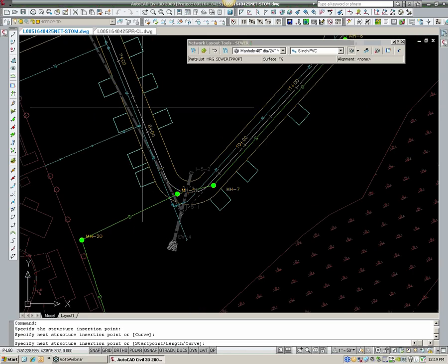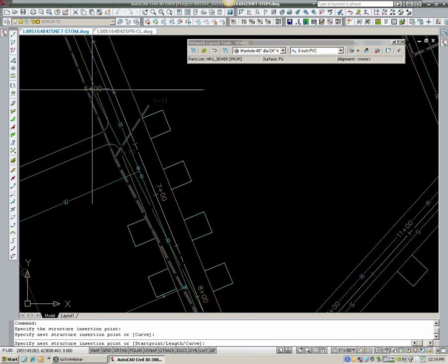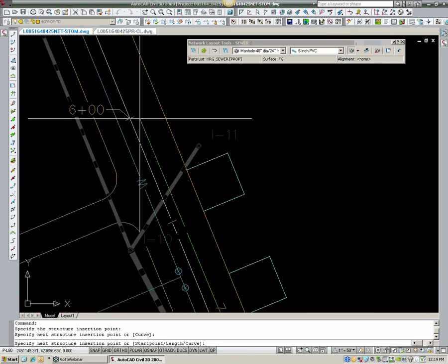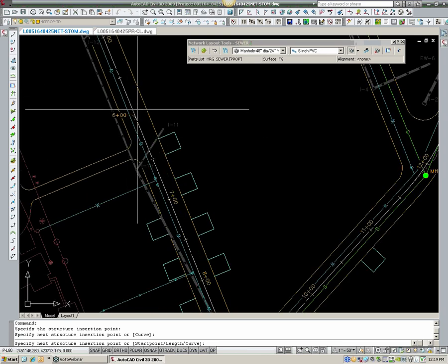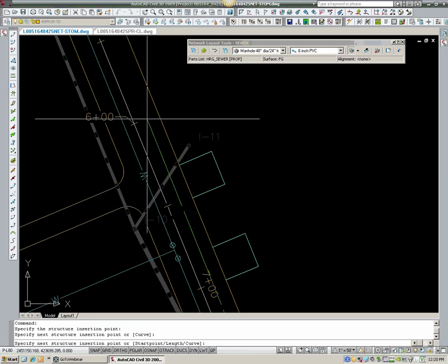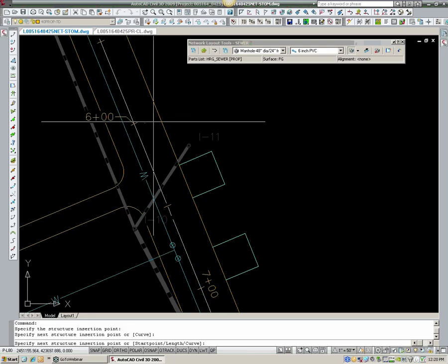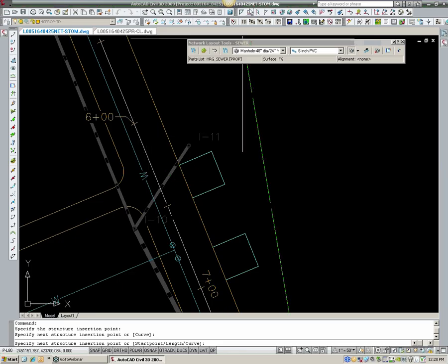Okay, well, I'm going to come up through here, and we can only go so far with our manhole run. So maybe up here around station 600, I want to place another manhole, because it can only have 400 feet of length and so on and so forth. But when placing this, just eyeballing these in, I want more precision than that. I want this manhole center to be right at station 600 and exactly 5 feet to the inside. I want it to be right here, but perfectly at station 600 and 5 feet to the side. So how do we do that?